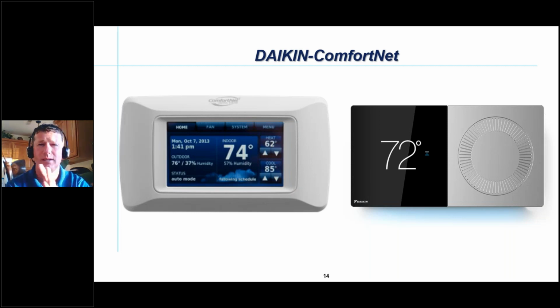So the thermostats were just really starting to get complex in how they operate and how they manipulate that HVAC system. But when we talk about the new Daikin 1 Plus, we're actually talking about a thermostat that is doing both now. So it is a communicating thermostat, so it's operating its equipment, the indoor unit and the outdoor unit, with that modulating 5-volt DC signal, and it also has switches internal. It has internal contacts, so it's using relays to be able to turn on two devices. It has two sets of contacts in its faceplate.